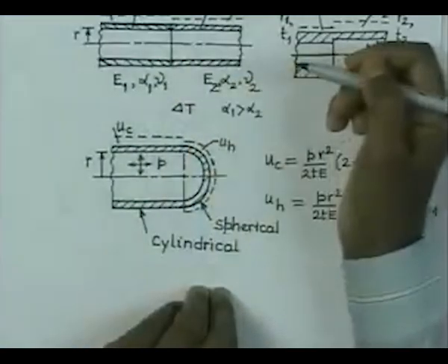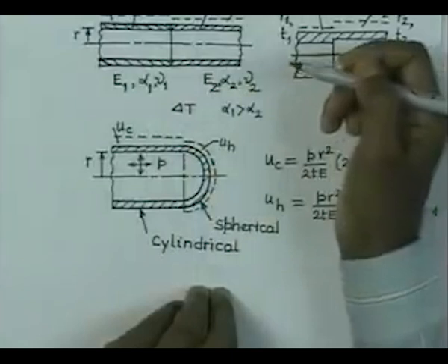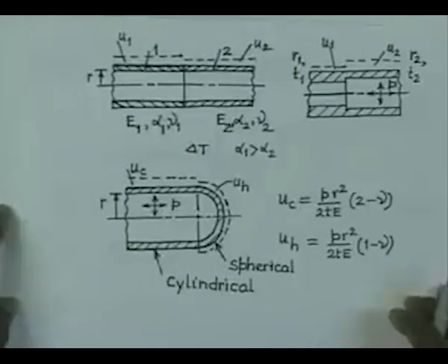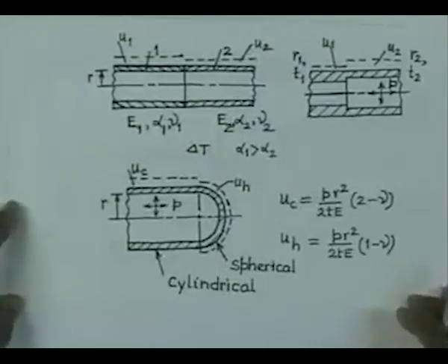So, on top of the stresses that you calculate by considering the hoop stress and axial stress, you are going to get some local stresses coming up here, and those local stresses are to be estimated. In all these applications you have a similarity, that you have some mismatch in the expansion of the vessel in the two segments, and you are interested in estimating the order of magnitude of the local stresses. In fact, it is possible to estimate the magnitude of these local stresses by using the analysis associated with beam on elastic foundation. So, that shows the importance of the topic.